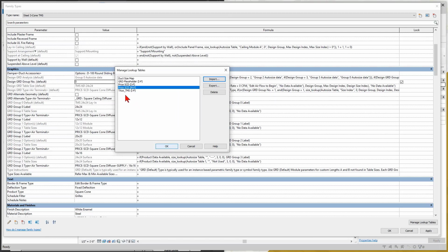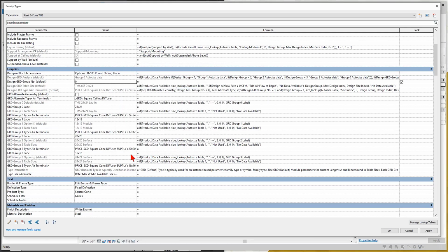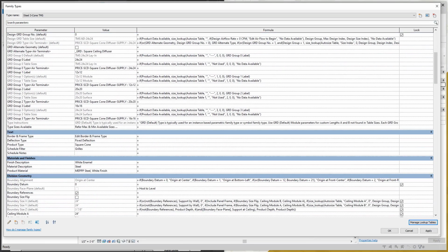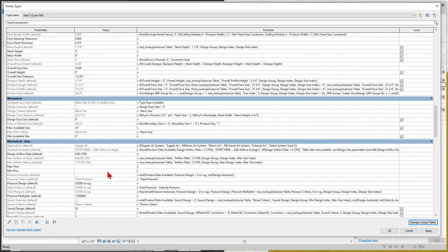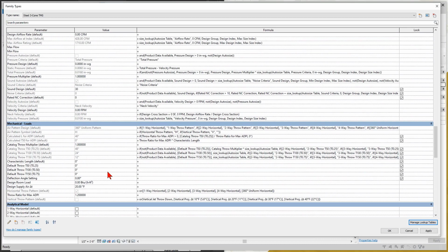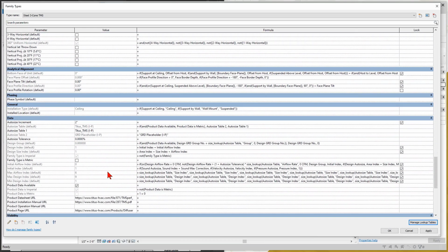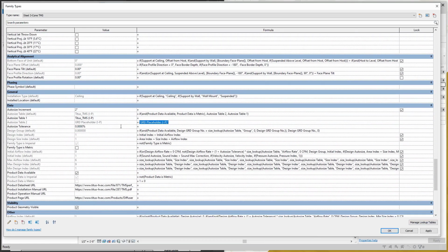Now I'm going to reference those, and then I'm going to delete the 2 that I don't need and just clean up some file space. So brought them in. They're not doing anything yet. We're going to see all this information up here changing in just a minute when I make this change from the TMS to the SCD files. It's going to reference all that SCD data and all the SCD lookup information here in just a moment. So we're about to replace a ton of data. We're going to do hours of work in minutes.